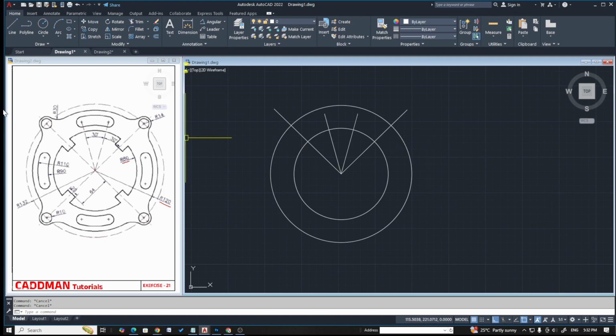And now either we can extend these lines in order to get the other two perpendicular lines, or you can select these two lines. There are different ways that you can create this. Or what I do is, normally I'll go for lengthen dynamically. I'll select here and go here. So lengthen dynamically and extend these lines till here.